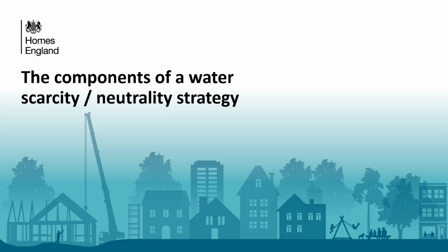So while water neutrality is a requirement in Sussex North and a de facto requirement in Cambridge, we've seen that water scarcity is a more widespread phenomenon. A new development in a seriously water-stressed area may need to be designed to a water use standard of 80 or 85 litres per person per day, which can add some costs to a development. But achieving water neutrality requires a much more comprehensive approach and is very challenging, time-consuming, and expensive. And we will have a quick trot through the key components of a water neutrality strategy.